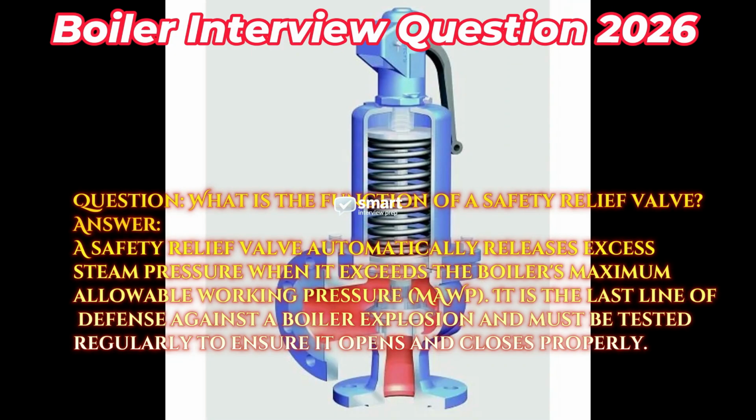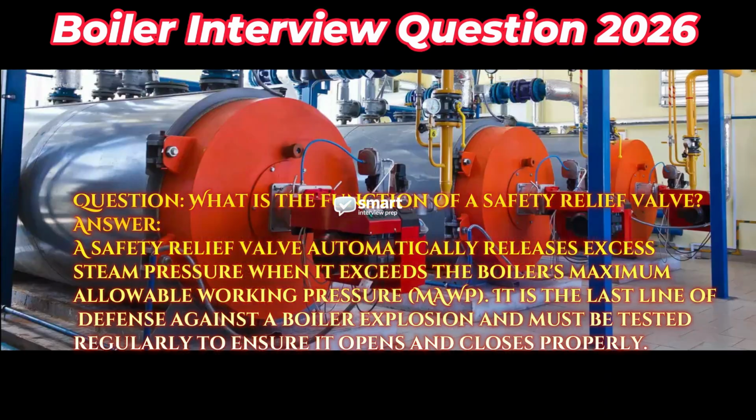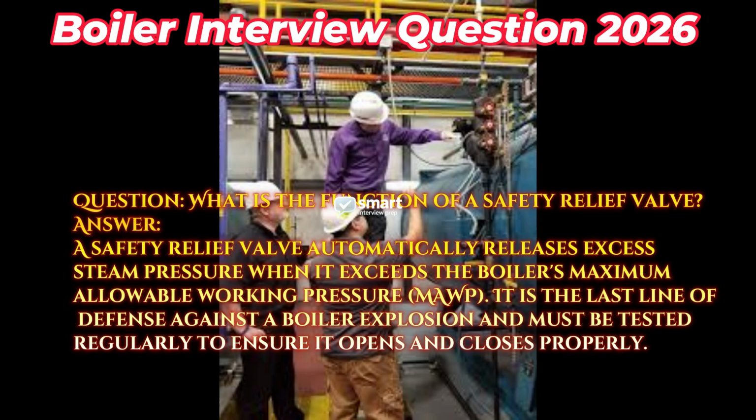Question: What is the function of a safety relief valve? Answer: A safety relief valve automatically releases excess steam pressure when it exceeds the boiler's maximum allowable working pressure, MAWP. It is the last line of defense against a boiler explosion and must be tested regularly to ensure it opens